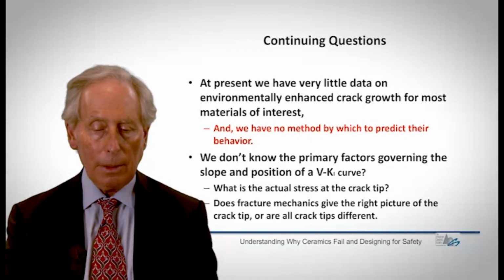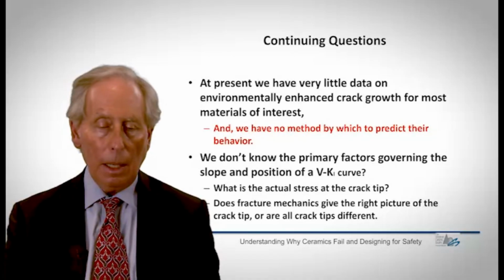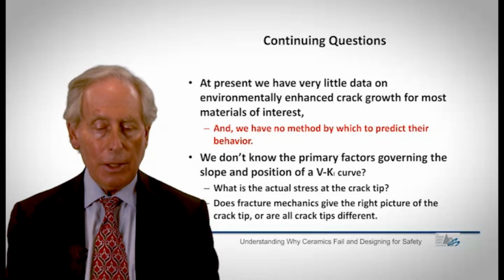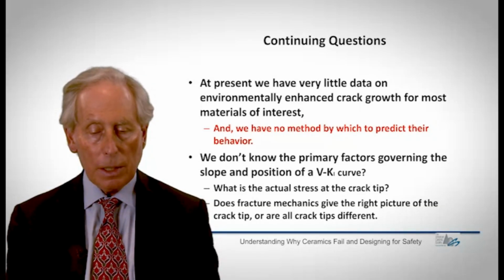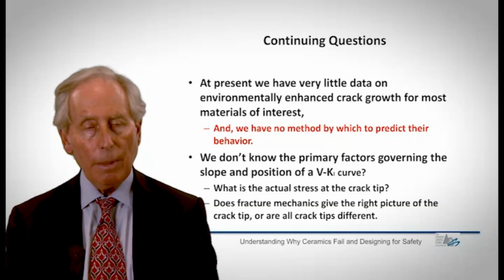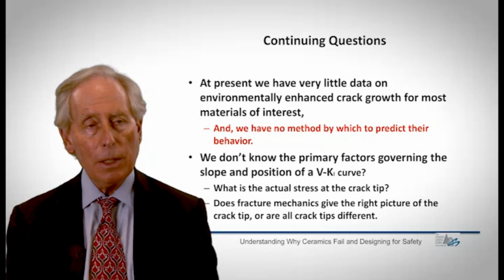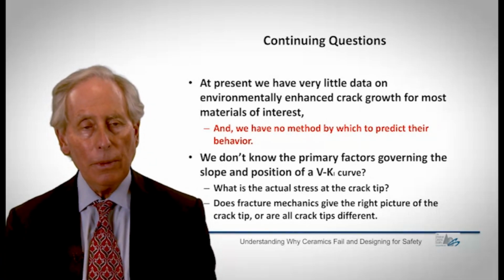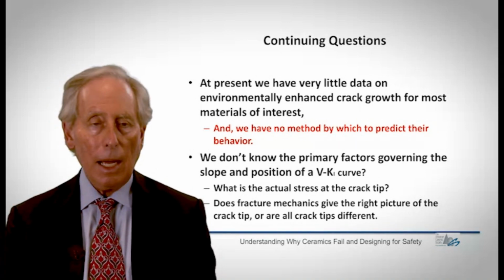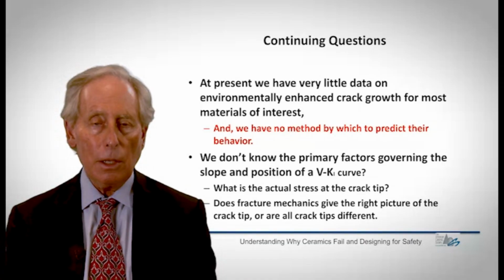and at what strength. I tried to present to you a method for predicting time-dependent failure of components along with the ability to determine the confidence in these predictions. In other words, I can predict failure probability. There are publications out there that say the time to failure for this material under this stress will be such and such.